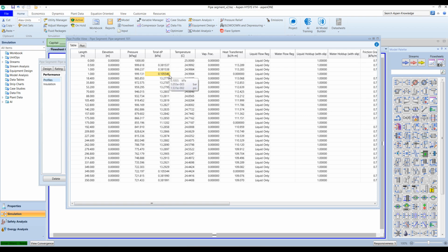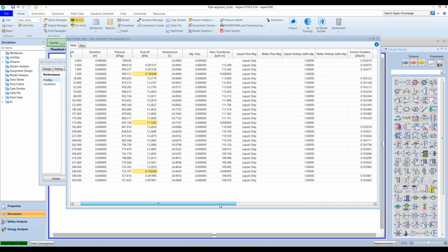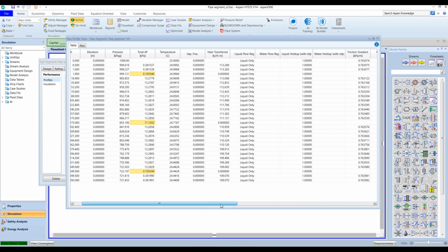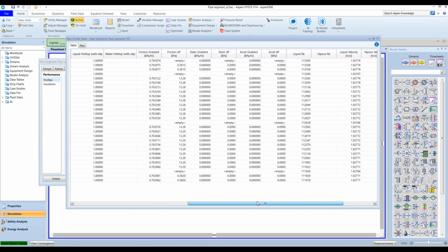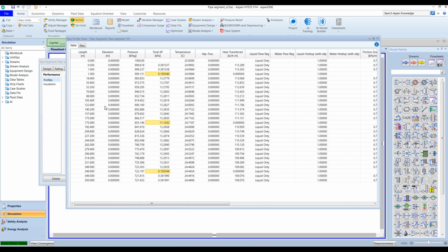So we've got this pressure drop across that valve. I would expect to have the same pressure drop across the other isolation valve. See that? These two match up, so they show me that this is the same fitting. But the biggest pressure drop is coming from that flow meter. In the middle of the line, it's got about 11 kPa. In this way, you can quickly see how much each fitting is contributing towards your overall pressure drop. How cool is that?